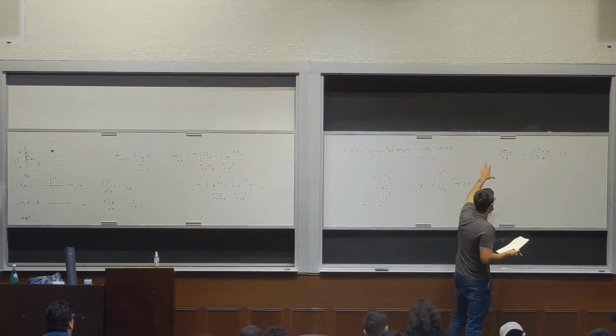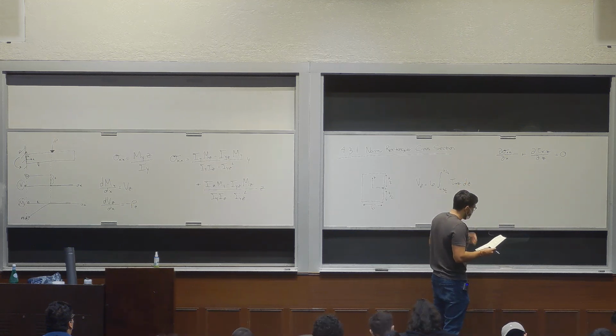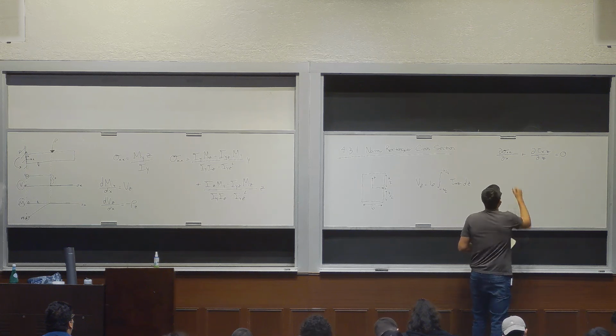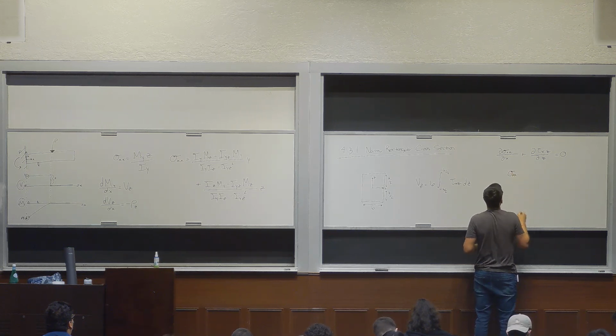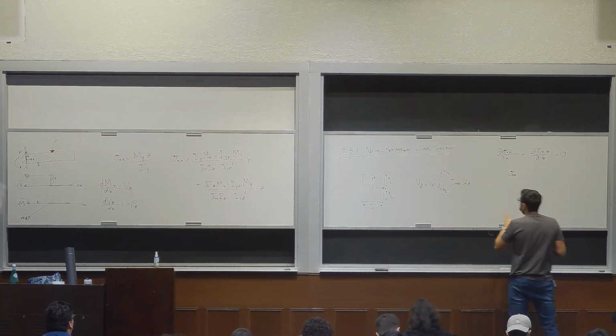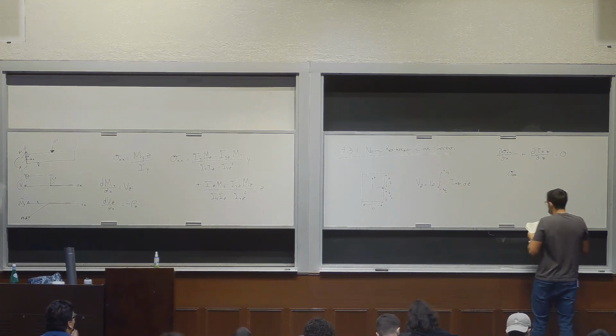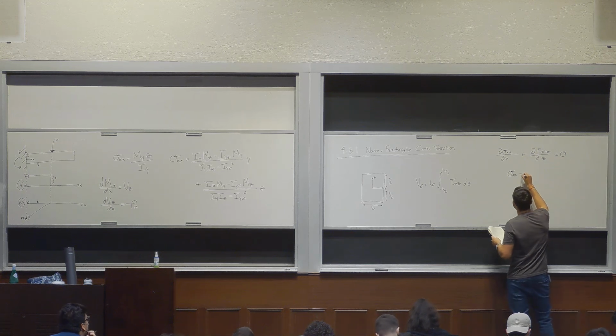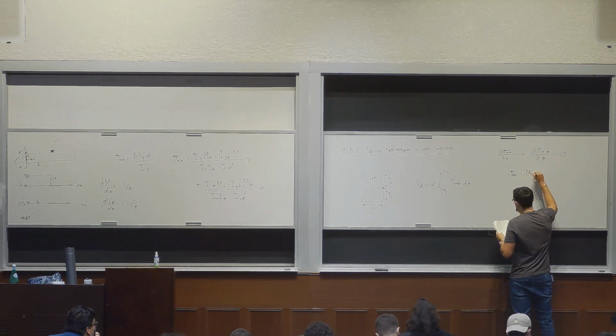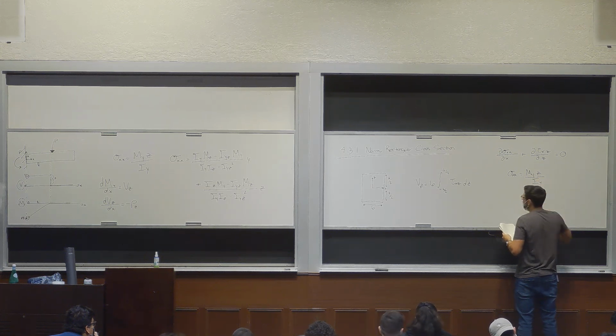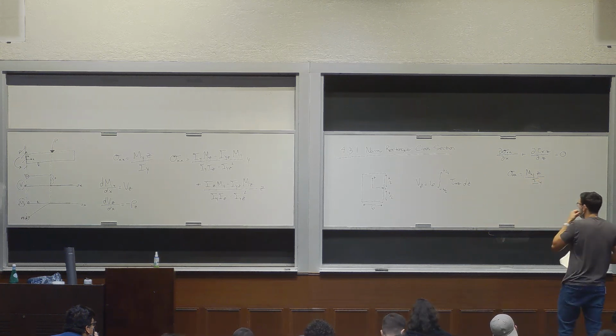Do you guys know the equilibrium equation? We also know that sigma xx, all we're trying to do here is find an equation for tau xz. Just follow with me here. So sigma xx we know is related to the bending moment: My times z over Iy.